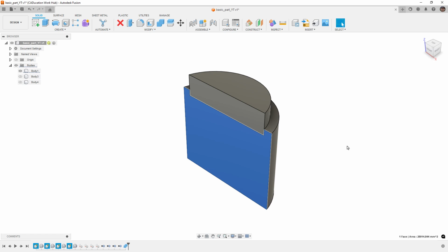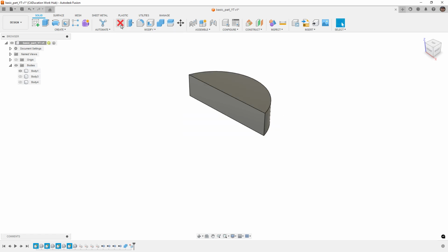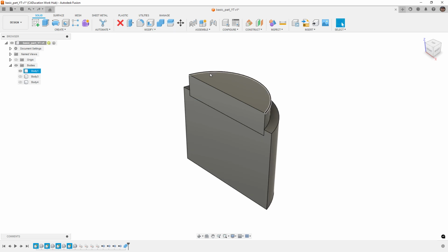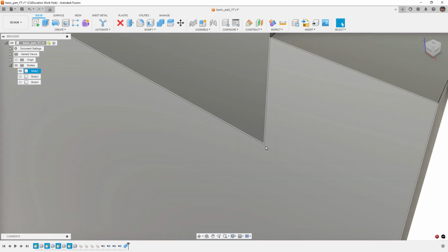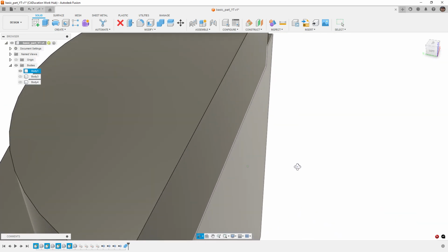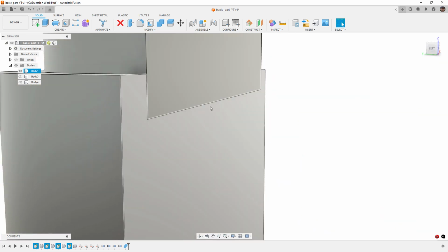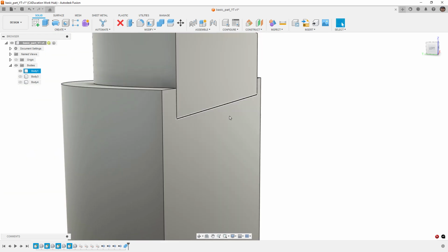One way that we can approach that in Fusion is by using delete. I'm going to hit undo and select this face and hit delete. And you can see that sometimes what we end up getting is these errors. This is because this is a very minimal face. But in reality, what we need to do is get both of these faces to be on the same plane.